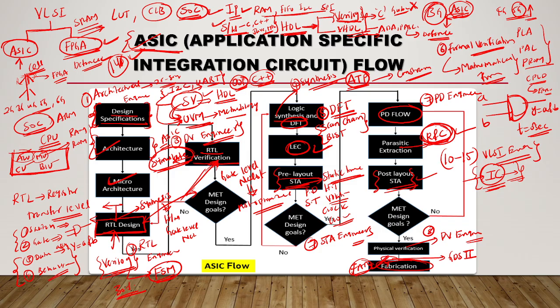Excuse me, sir. Yeah, tell me. So you mentioned formal verification, no? Is it done in pre-layout or LEC? In the front end they will do. Here in the verification, RTL verification is there, no? This is nothing but what we call design verification. Design verification means you are using UVM methodologies to verify the correctness of the circuit.